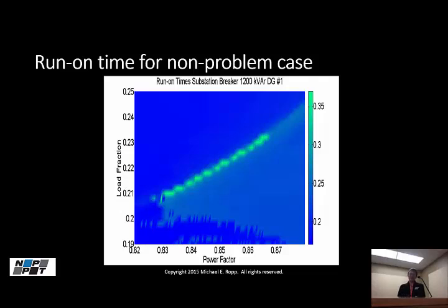This case, I may mess this up. I'm trying to remember how all these cases fit together, but I believe this one was a case with two PV plants on the feeder, no rotating machines, and it was 2 different manufacturers, but they were using approximately equivalent anti-islanding methods. So even with the 2 inverters and several inverters on the feeder, no issues. They saw it just fine. So this is a case where things worked the way they were supposed to. Here's a case where they didn't.